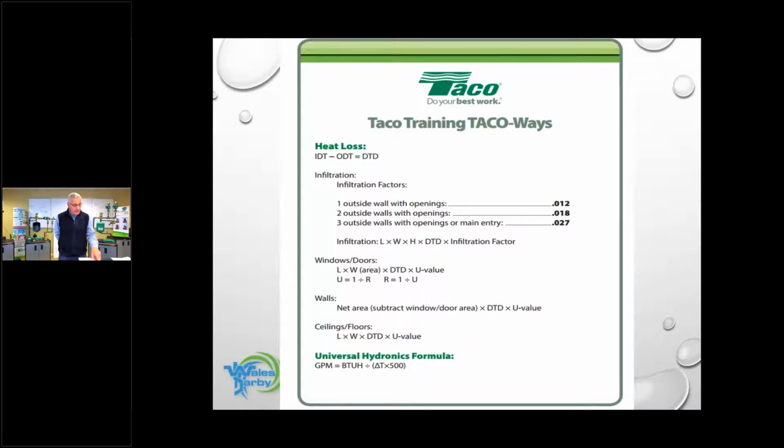So if I divide 1 by 19, I should get 0.053. All right, so make sure you're doing this with me. So take 1 divided by 19, and I should get 0.053. So if I take that math, the 150 minus 30, I take away my windows, that leaves me with 120 times 56 times 0.053, I'm going to get 356.16. Write that number down.